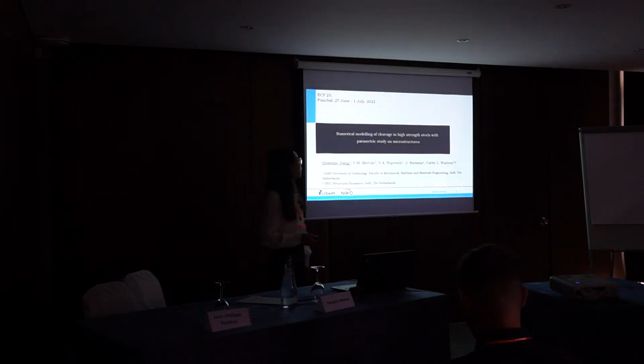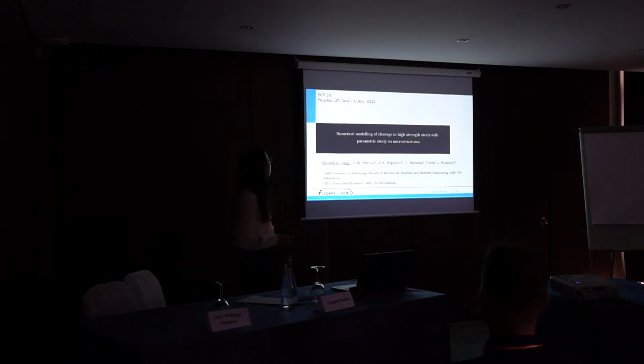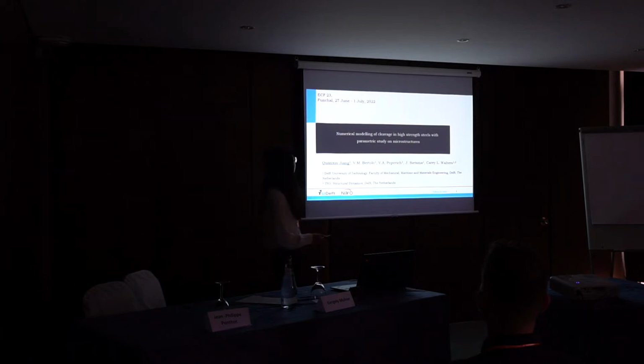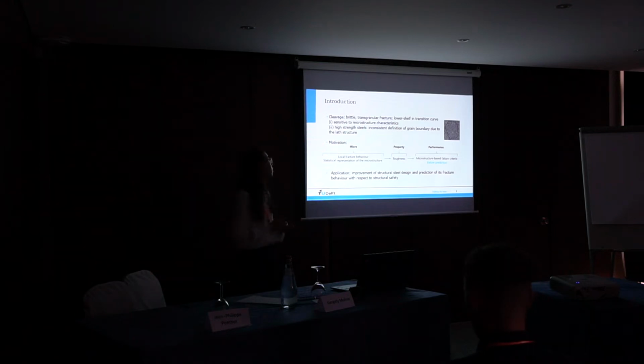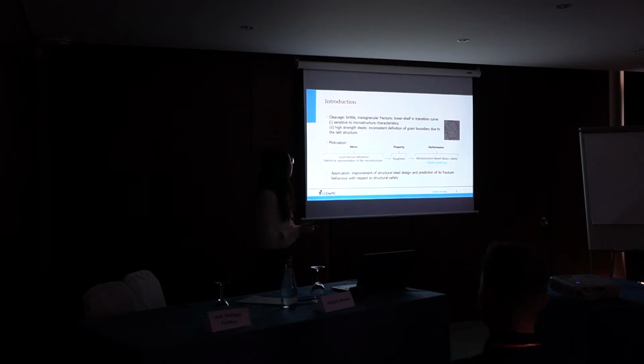Modeling of cleavage in high-strength steels with a parametric study on the microstructures. Our research focuses on cleavage, which is a brittle and transgranular fracture related to the lower shelf fracture toughness of steels in the transition curve. We are more interested in the initiation of the crack, because crack propagation occurs at a very rapid speed, so we focus on the fracture toughness at initiation rather than the propagation of the